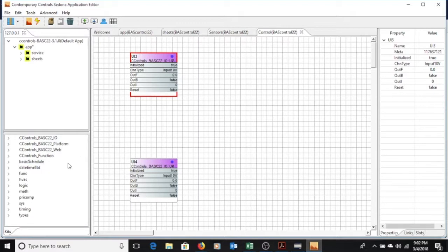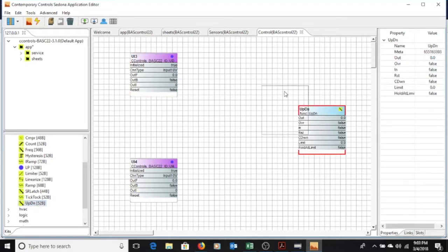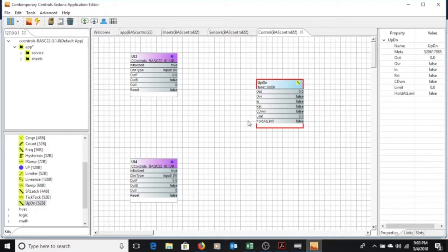like your regular thermostat. How do I get this thing to pulse up? How do I get it to pulse down? We have to create eventually a set point. So when we look at functions, I have inside of here a function of up down. Well, one of the things when you guys were getting into this originally is that on this up down, it counts a lot. It thinks too digitally out here, so push buttons going into it can be kind of tricky.